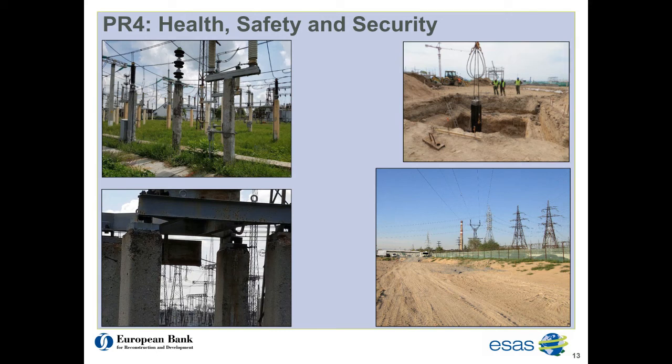Loads are being lifted near live conductors. These live conductors are not tagged or wrapped. And again, safe approach distances are not defined and barriers to prevent access are not being used.